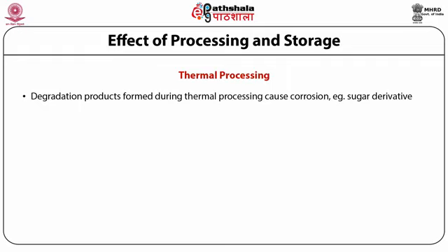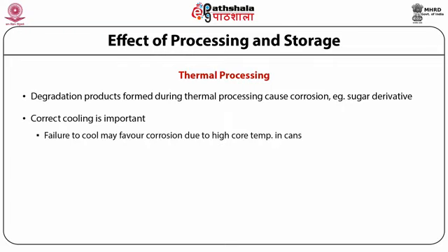What has been emphasized is the importance of correct cooling. Failure to cool cans adequately can lead to increased corrosion, since the can center temperatures may take several days to return to the ambient temperature. On the other hand, cooling to too low a temperature may cause paneling of the can walls as well as external corrosion, since complete drying of the can